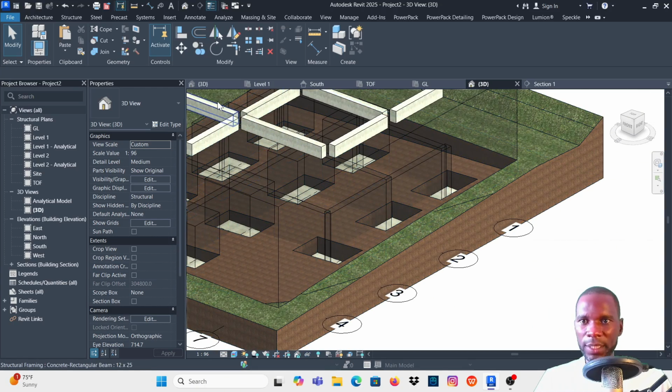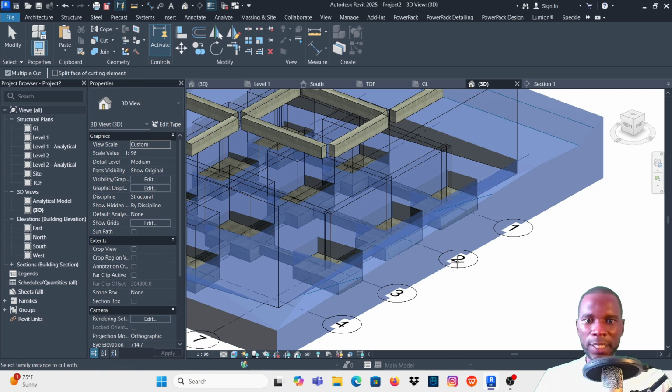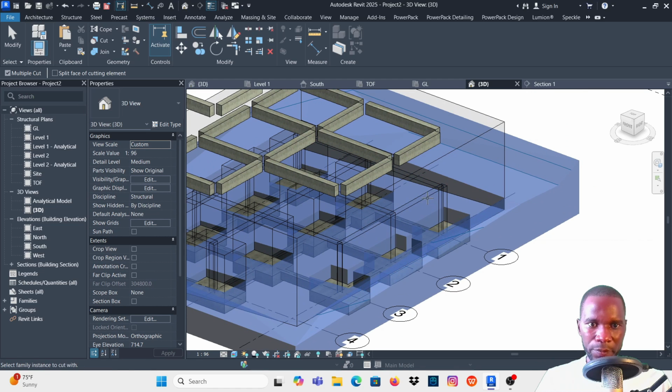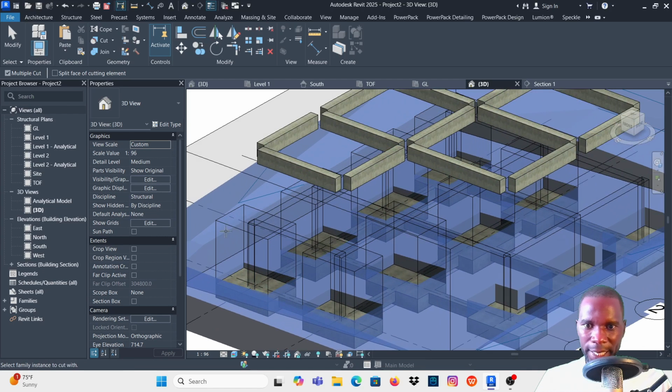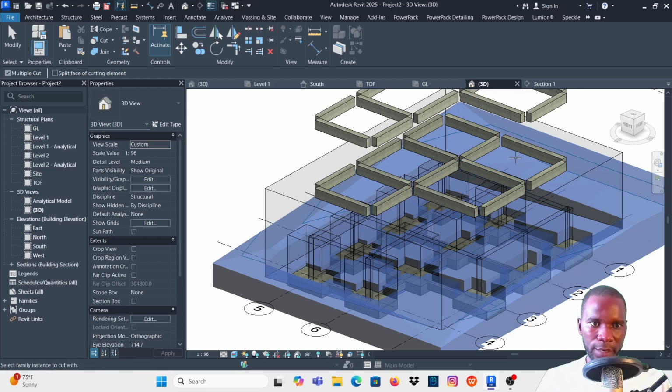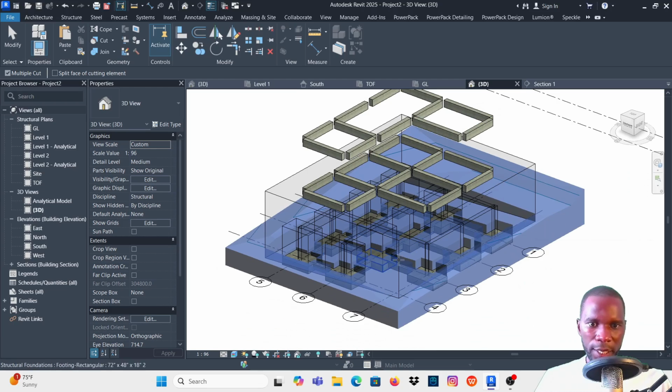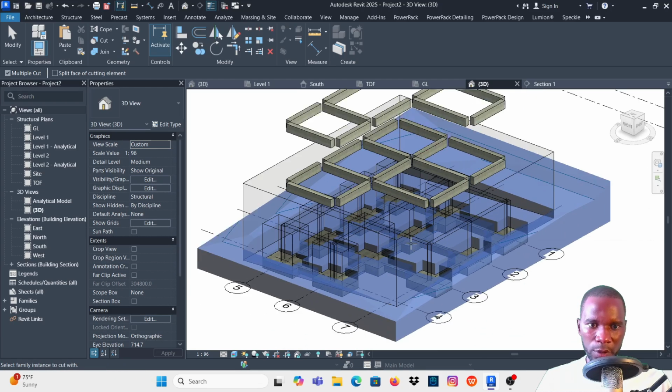Now, what you need to do to excavate this, just go to cut geometry and pick the excavation there, the toposolid. Make sure that the multiple is selected. Now you can start picking these. You can even see that it will just highlight the ones which haven't excavated the toposolid. To not pick the ones for the bases. So as you move it, you can simply see what you are supposed to excavate. What else is remaining? I think everything has been, oh, this one here.